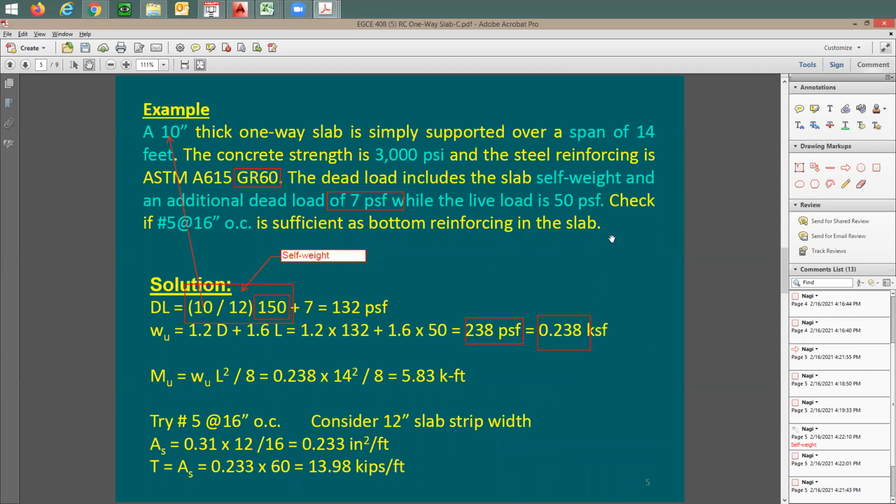If you like to consider here a 1 foot strip, right? Just imagine here is a 1 foot strip. And here's the center line of the support, just like I'm looking from the top, like a plan view, right? The distance from here to there is going to be 14 feet. Now I have taken only 1 foot, which means this number here is true.